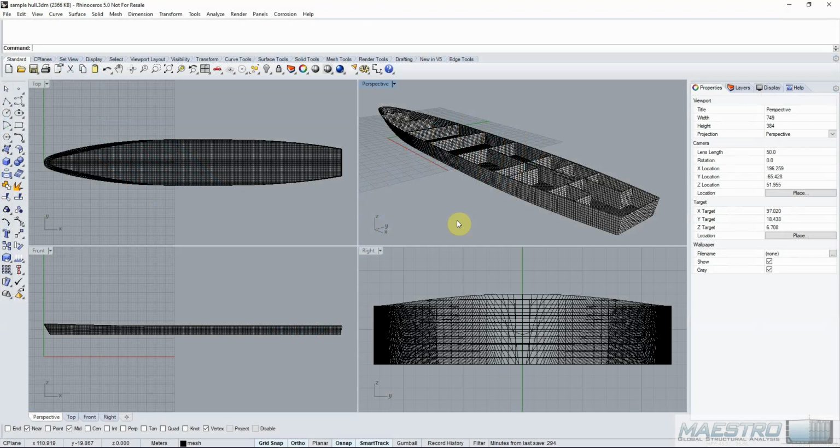Now that we've reviewed all the options for the script, let's move on to a more practical example using a sample hull form. Here we have a mock-up of the second deck of a vessel approximately 160 meters in length. We've added transverse subdivision bulkheads every 20 meters along the length of the hull, as well as some additional longitudinal and transverse structural bulkheads in the after portion.